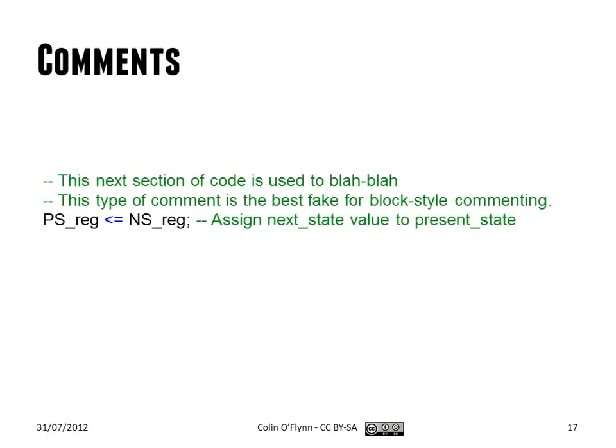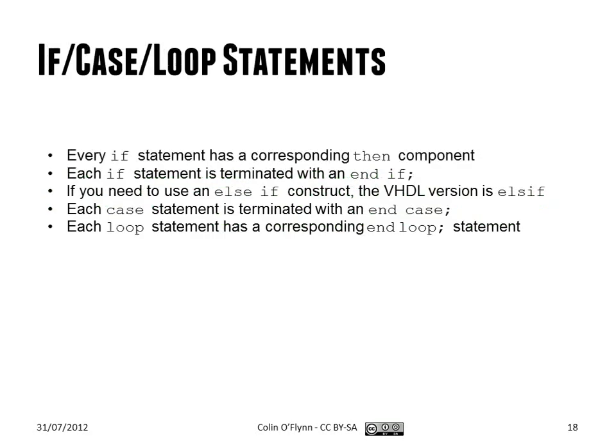You can add comments, and you'll notice that with --. The editors you can use, and you can use that same Xilinx software for doing this, will make comments appear in green so that they sort of blend away a bit from it. And we'll go into this a little more detail. You have statements, a lot like in C. There's if statements, there's case statements, if-else statements, and there's even loop statements, which I'll talk about later.